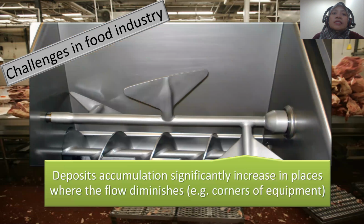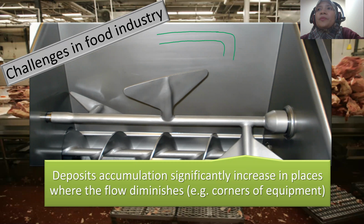Food salts is easily accumulated in food equipment, especially when the flow diminish. Okay, where there is a turn, where there is a corner within the equipment, such as within the pipe. Okay, so let me draw here. Okay, let's say we have a straight pipe, but if suddenly you have corner like this, okay, normally at this place, where there is, we call it a dead zone.